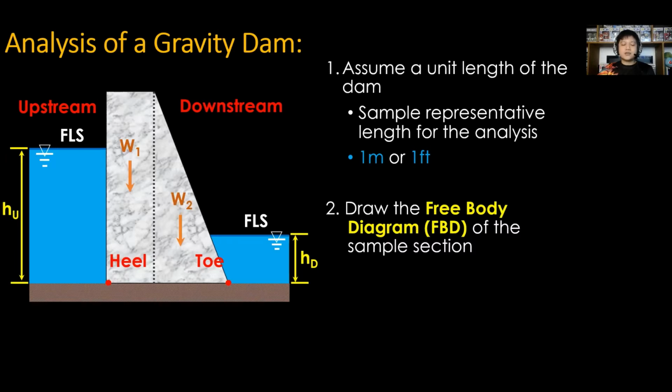For hydrostatic forces, consider only the portions exposed to water. For inclined or curved surfaces, it is better to consider components of the hydrostatic force. A sample is the forces at the downstream side. If the foundation soil is permeable, then determine first the pressure values at the heel and at the toe.